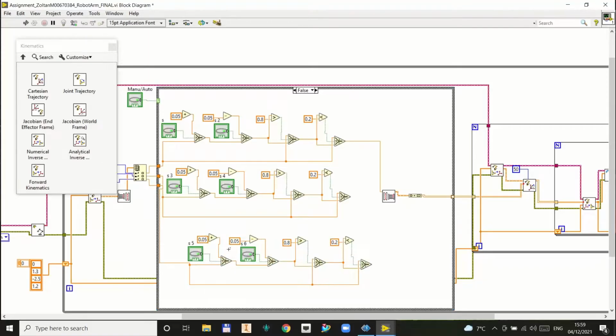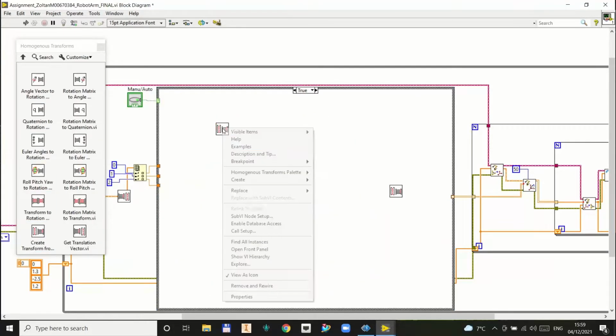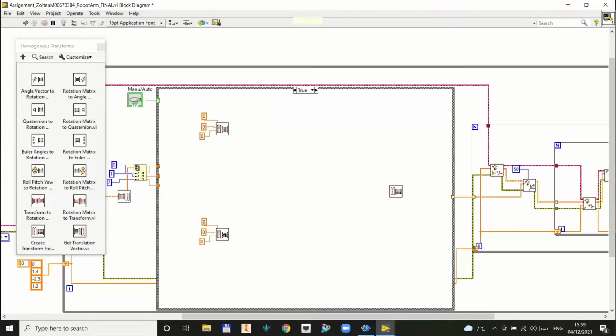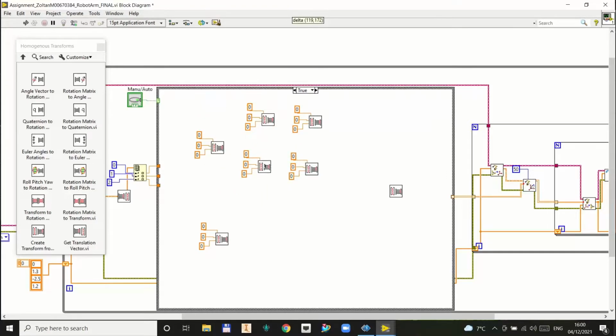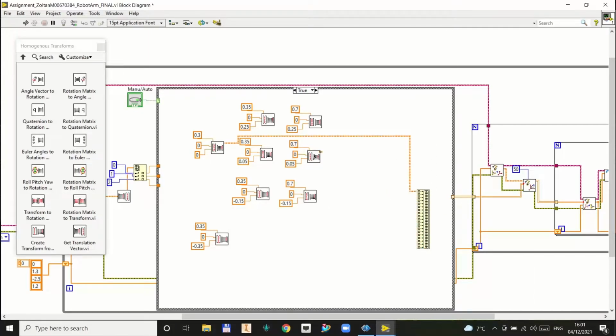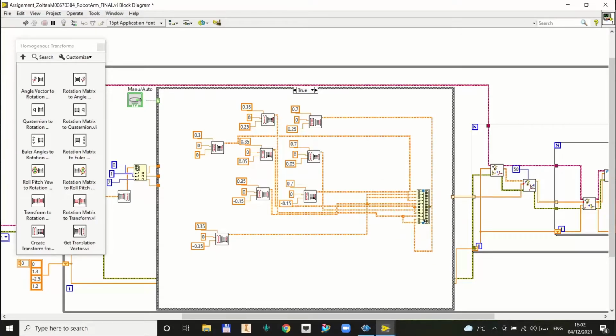Preset coordinates are sent to the for loop as an array for the trajectory planning block. Preset values in order are home position, floor, first shelf offset, first shelf, second shelf offset, second shelf and so on. This way the robot will move to the floor level to pick up an object, move to in front of the shelf before placing the object and then back out, and repeat with all 3 shelves.